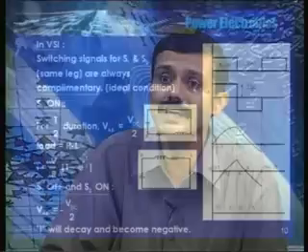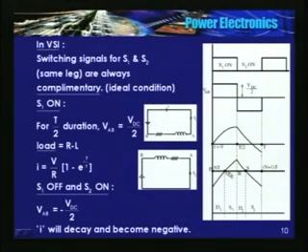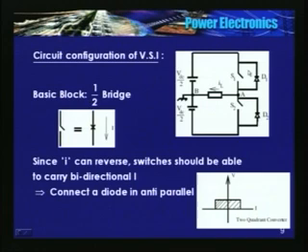Current starts flowing through the device, or S1, only after Q. Say from Q to R, voltage is positive and current is also positive. So it can happen only if S1 is carrying the current. Because the voltage is positive, this point should be connected here, and current is also flowing in this direction, so S1 is carrying current.